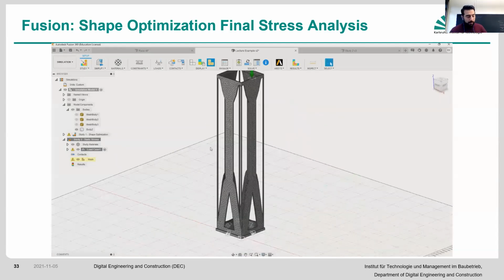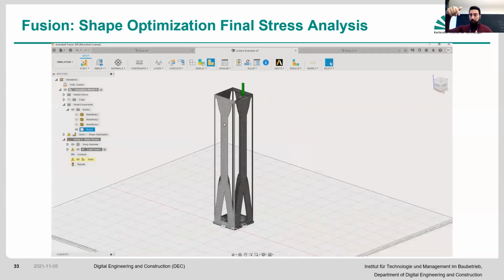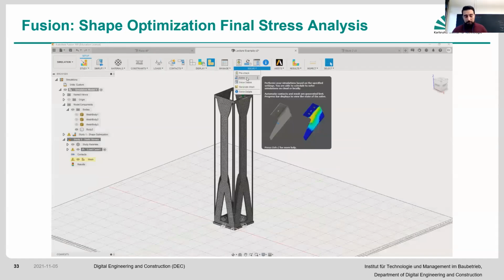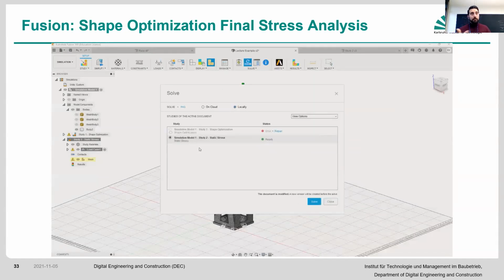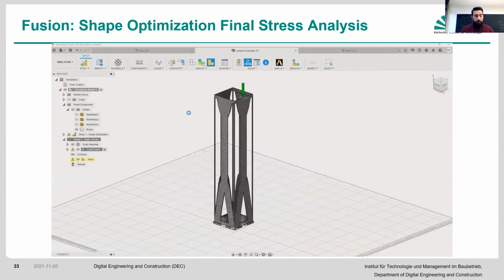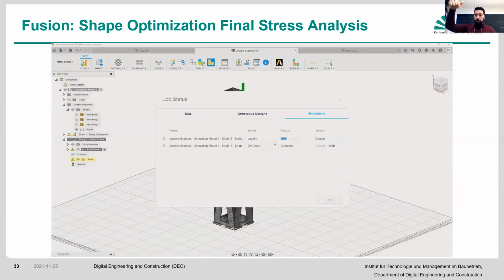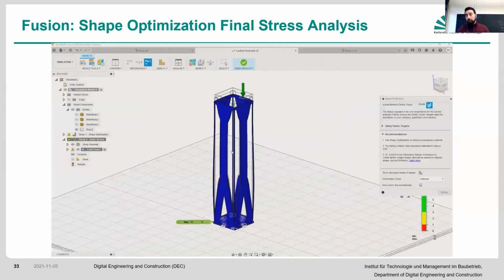And as you know, if a structure is subjected to an axial load, the amount of displacement is going to be PL divided by AE. P is your force at any section, right? L is the length of your element. A is the cross section at a particular cross section that you're considering for your stress. And then E is your Young's modulus.